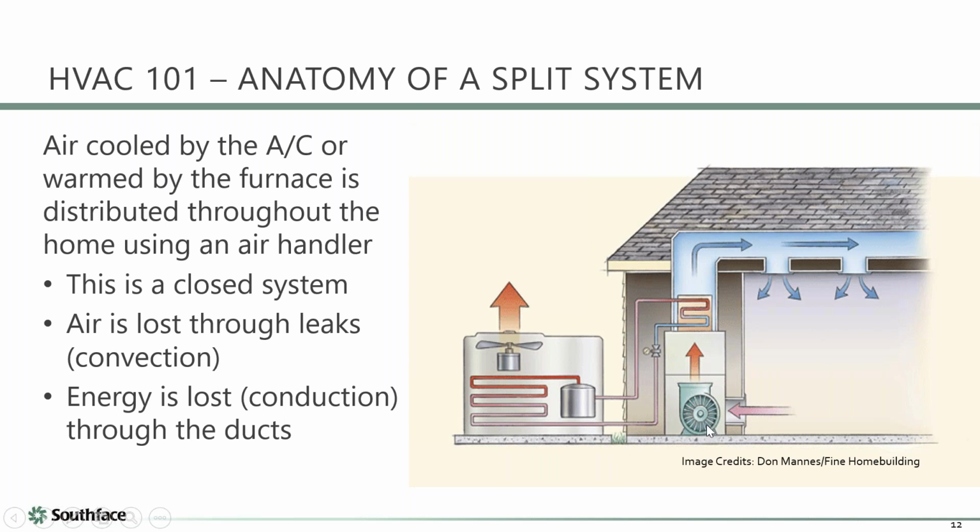Today, I believe any furnace you buy inherently comes with an ECM blower, but not necessarily every heat pump you buy. So the easy thing to do is to get an ECM blower, a variable speed blower with a thermostat that can smartly adjust it. Or if it doesn't have that feature, like my furnace, which is a condensing furnace.